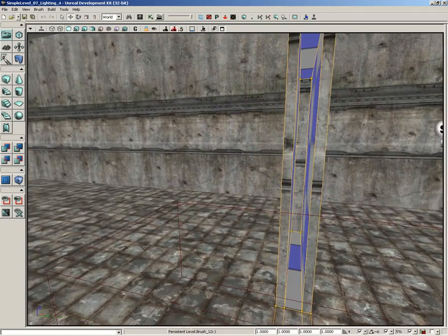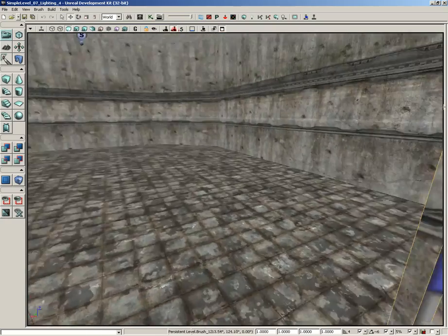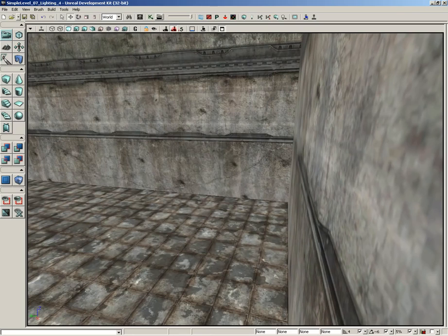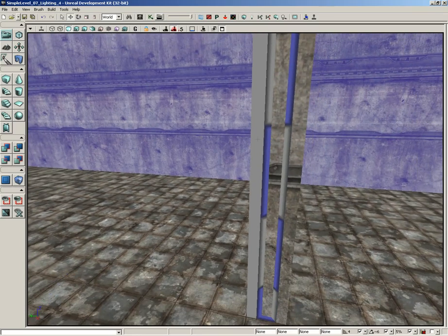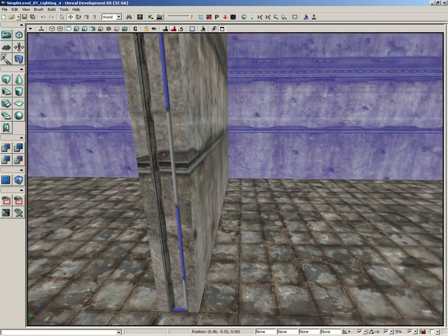And you'll notice that because I didn't have a material selected, we're getting that blue checker all over the inside of our pockets, which is no good. Now to fix that, I am going to do kind of a trick. I'm going to select a surface, hold down the Alt key, and right-click on it, and then come over to any other surface, still holding Alt, I'm going to left-click on it, and that's kind of like copy-pasting materials.